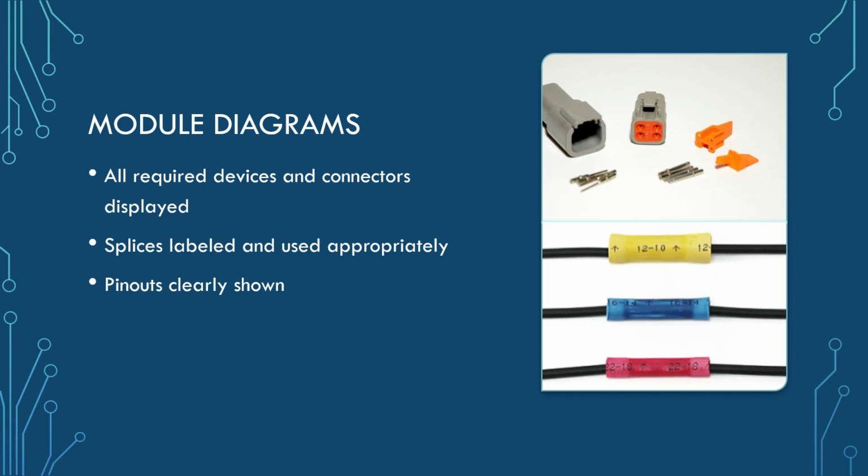And as I mentioned earlier with the module diagrams, we try to keep the harness modular. Let's say at a competition something happened with one of the sensors and it broke, and having it on there is more of a danger when driving than not having it. Because it's a modular diagram, we can just clip it off the original harness using one of the Deutsch connectors. We don't need to use it, it's not going to be a hazard, we don't need the data, and we can easily take it out or even replace it with another module if we wanted to.